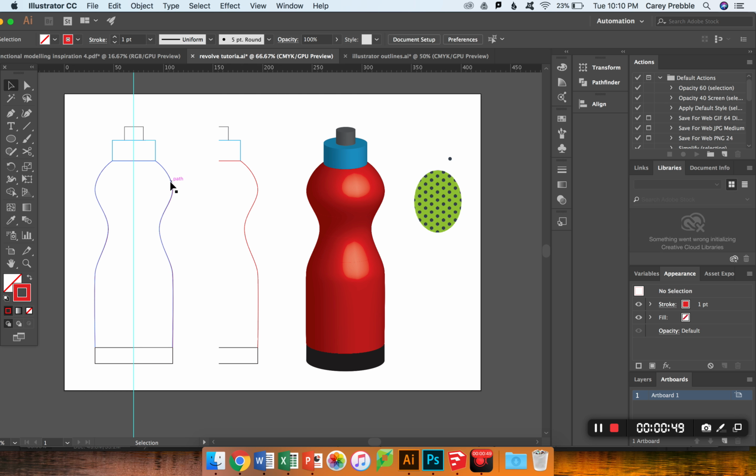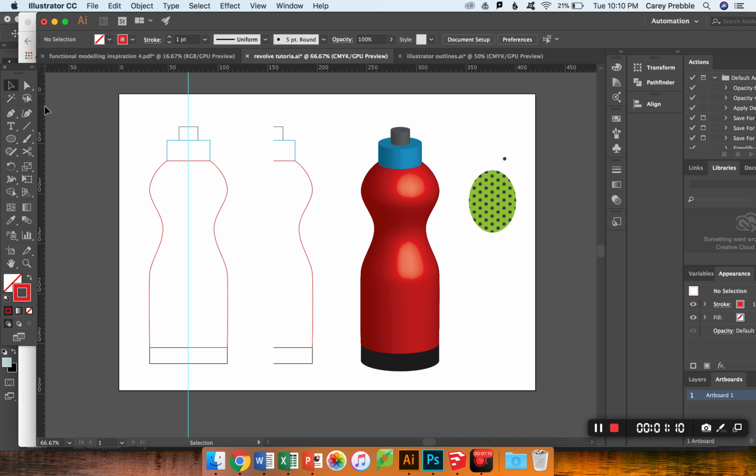The next thing that you're going to do is divide your 2D sketch in half. In order to do that, what I usually do is I press Apple R, and that brings up these rulers that come across here, and I just drag one of the rulers across like so, and I snap it so that it's in the middle, like this one over here is.